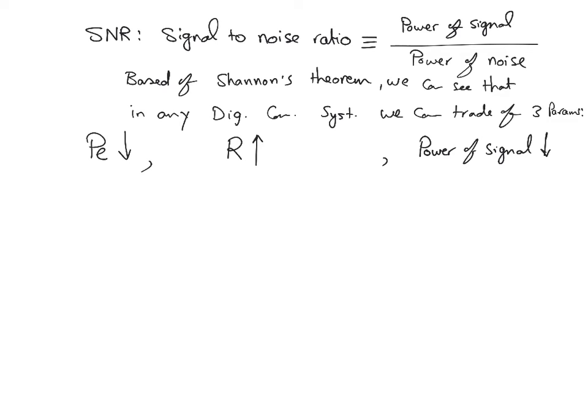So these medical images have to be communicated highly reliably. In that case, it's okay, I will spend a little bit more power, and I will give away a little bit of the transmission rate such that I guarantee that they arrive there with very high reliability, because that's more important. So again, the three are traded off, because they are contradicting objectives.